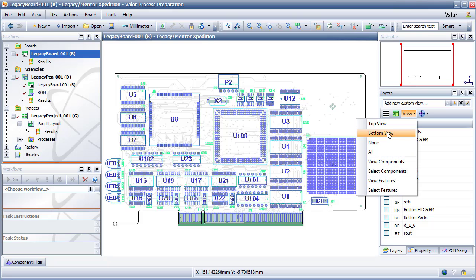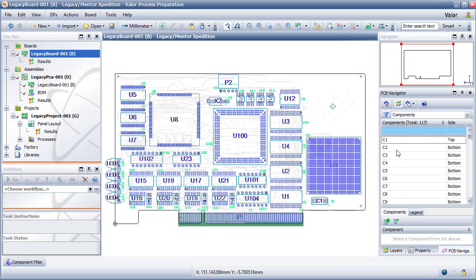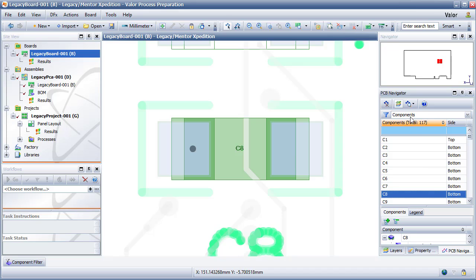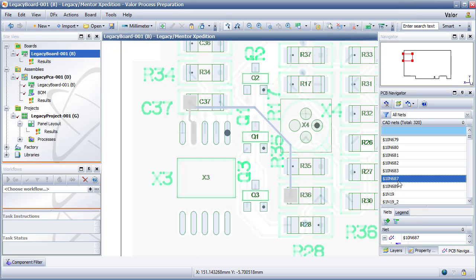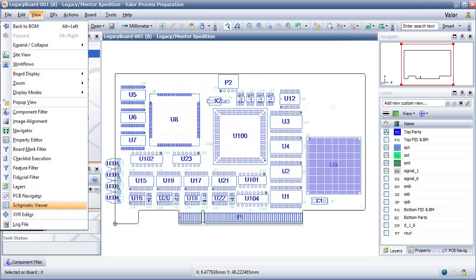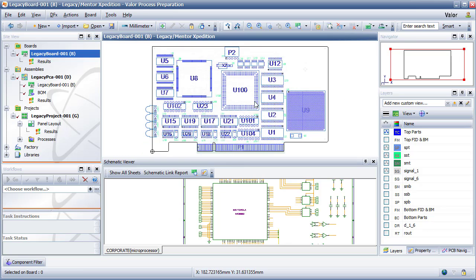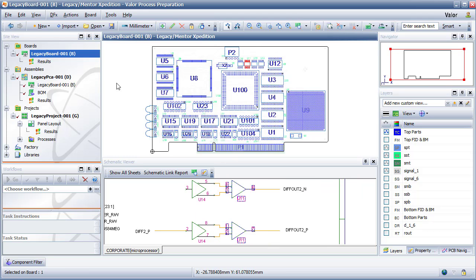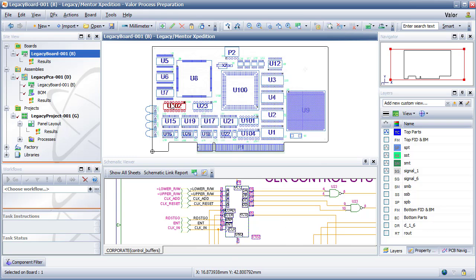First, we see the board itself, which is usually created from some form of CAD import. However, it can also be created from Gerber files, provided they are processed through component extraction and netlist derive functions, both supported by Process Prep. Each PCB layout will have been created based on a schematic design. This schematic data is critical to electrical test, providing additional data not typically delivered in the physical layout, namely pin functions, such as anode and cathode, or base, collector and emitter.